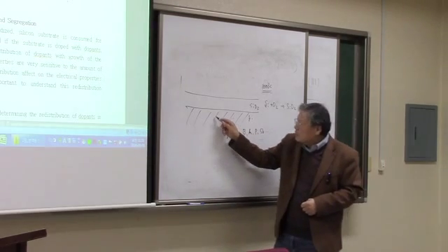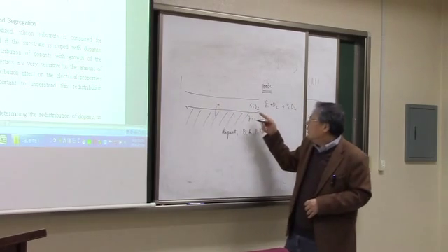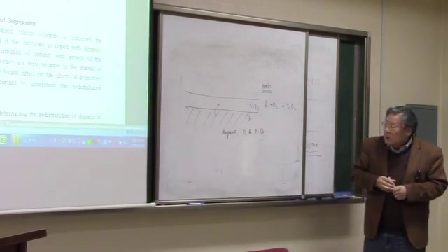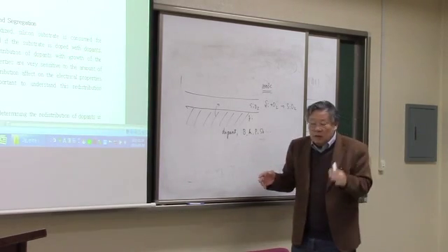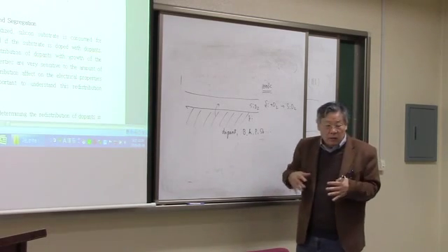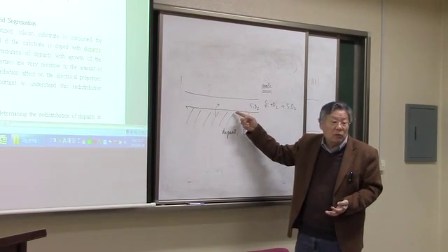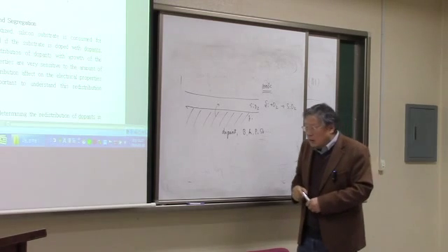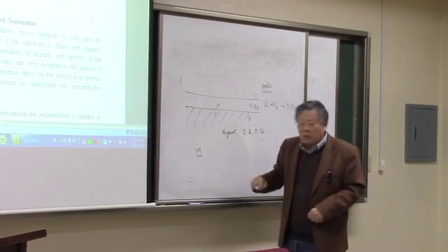Now, this dopant is going to be incorporated into the silicon oxide. Okay, so that's what we call, in this text, redistribution of the dopants: how the dopant atoms are going to be incorporated into the silicon oxide. Okay, and that's very much dependent on the value of the segregation coefficient.